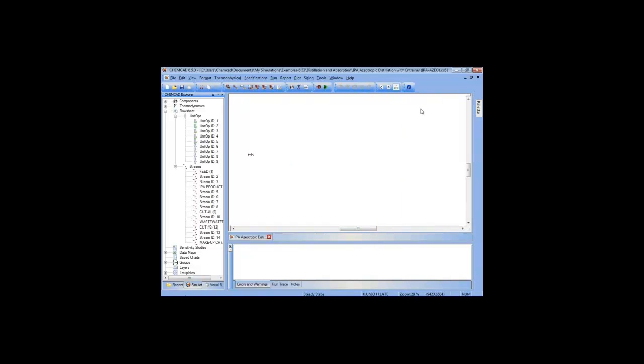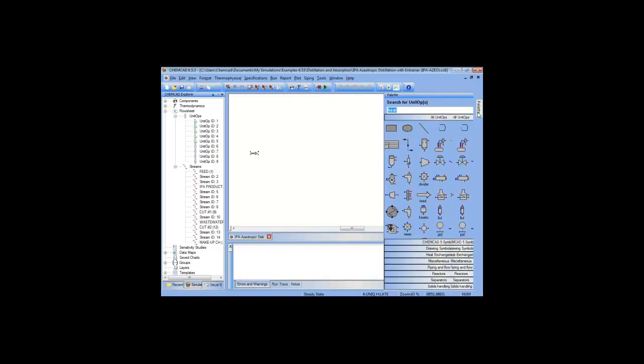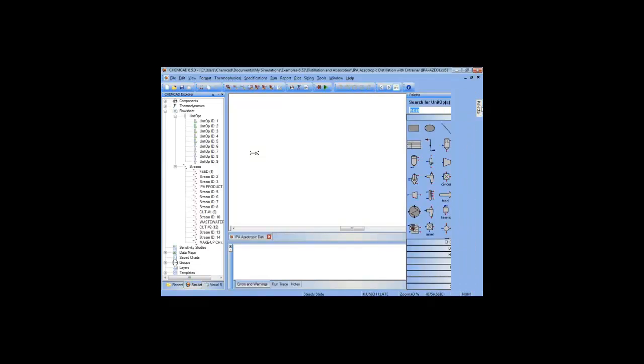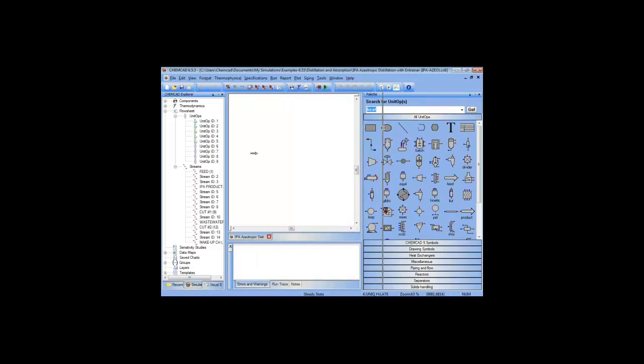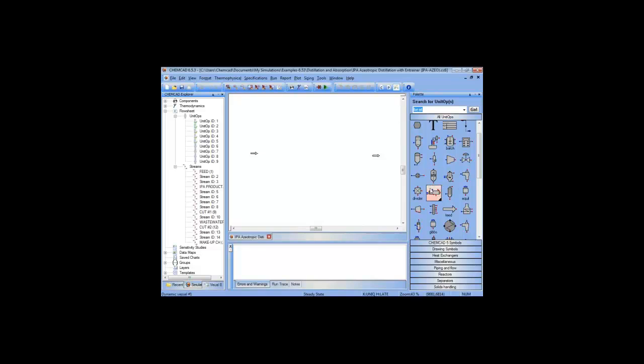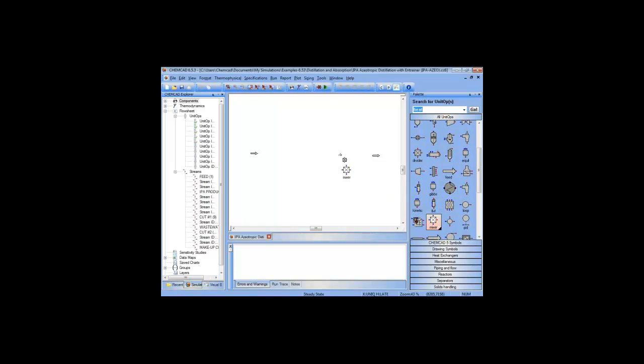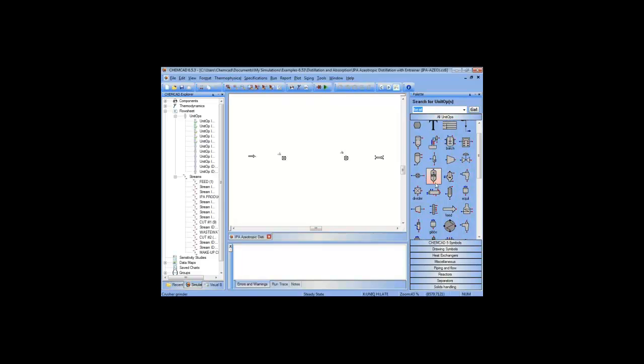I'm going to start by drawing a recirculation of flow. I'm going to have a stream of water and ethanol, which is being separated by a divider, and then use a mixer to mix it again. So I start with a feed arrow and a product arrow. I'm going to pin the palette, makes it easier to draw. I'm going to find the divider unit, and I'm also going to find the mixer. And just so we have something happening on the flow sheet, we'll add a heat exchanger. This is going to be a very simple process. You wouldn't normally have something this simple.